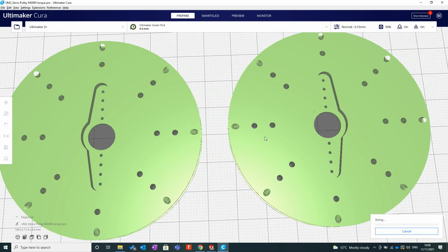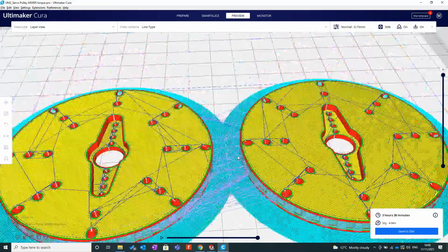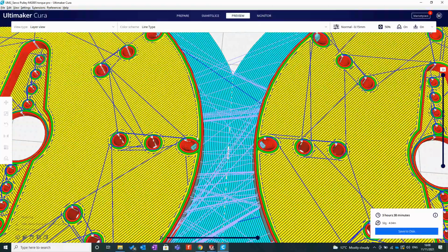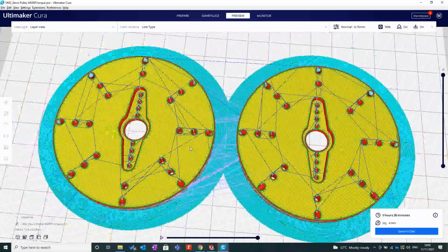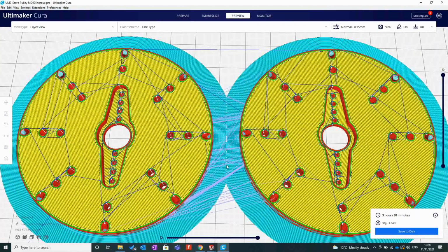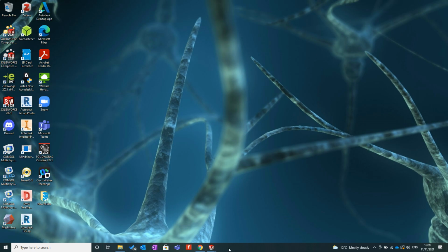And if I slice this, let's see how it gets on with slicing. Let's do preview. Yeah, it's not done me proud there at all. You can see there that it is pretty sweet. It's done a cracking job. Damn it. But if you're doing something like a faceplate, something that has a lot of profile to it, and you're losing detail when you're converting out in a binary format, then I would always recommend trying going through the ASCII format, because the ASCII will just give you that little bit of an edge. But I've not chosen the best real example for that, because I'm just making it up as I'm going along.